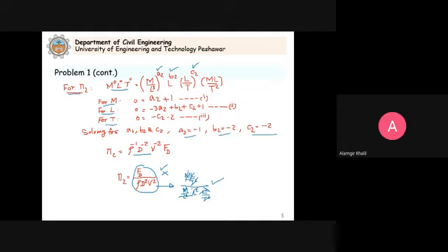If any dimension is remaining here, it means you have made a mistake. Go back and see where is the mistake. Why should you not get any dimensions here? Because by definition pi has no dimensions. So if we say left hand side is equal to the right hand side, then in that case the dimensions must be identical on both sides.